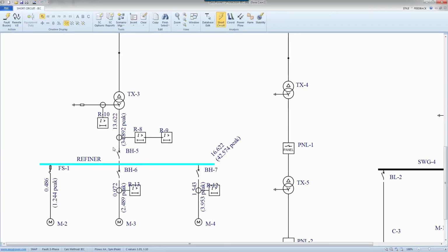So by replacing the frequency of, let's say, 60 with 24 hertz, the R value remains the same, the X value becomes smaller, and that's what method C does. It replaces the X value for the positive sequence of all these branches with a value which is 0.4 times the original value of X, keeps R the same, combines these values, finds the equivalent Z, and then divides that X by 0.4 again.